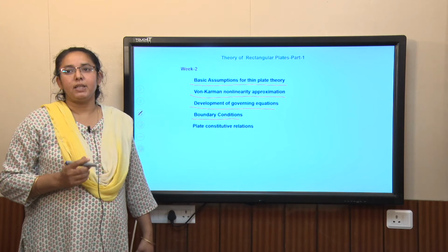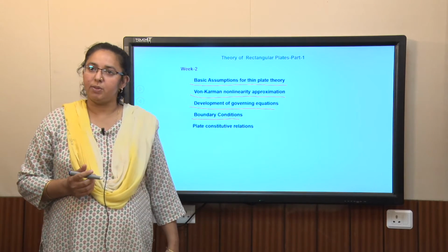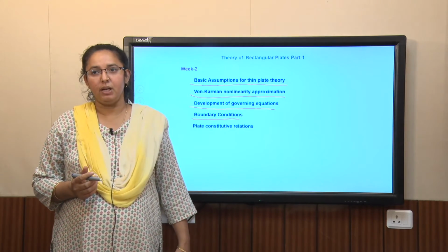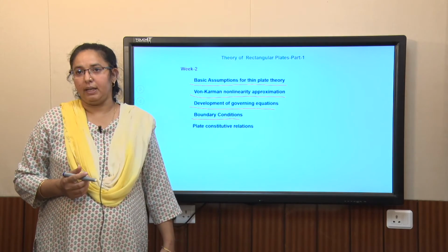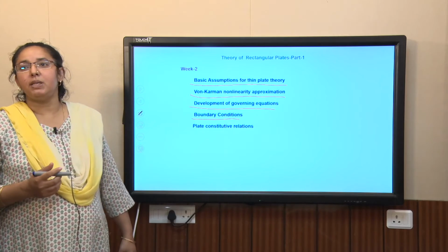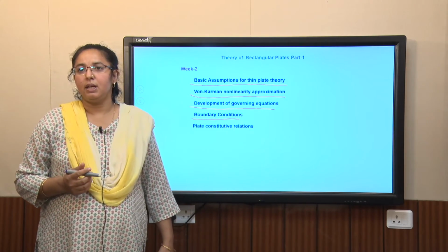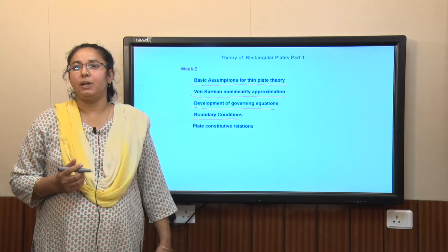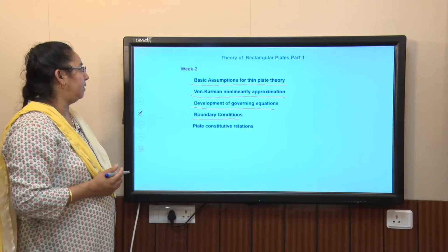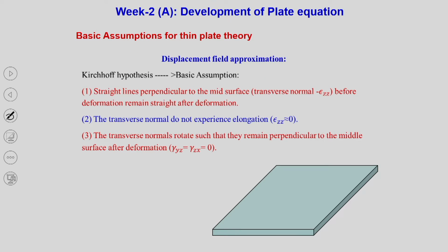Till date I have explained to you what the virtual work displacement is, what the Hamilton principle is and how to apply that. Now we will learn, for a specific case, how we are going to use the Hamilton principle to develop the plate solution, the governing equations. So first, the basic assumptions for a thin plate theory.